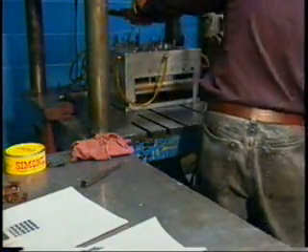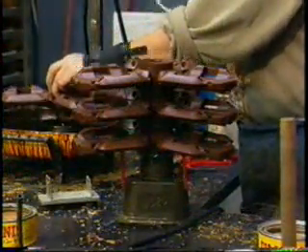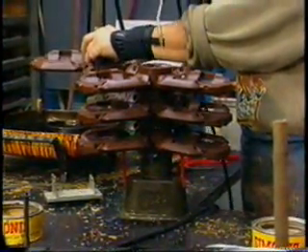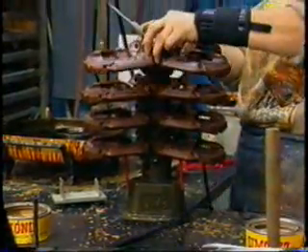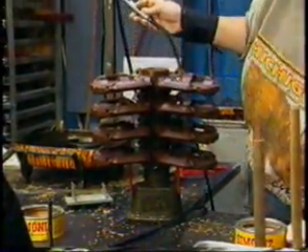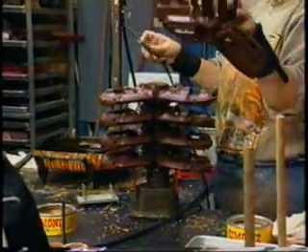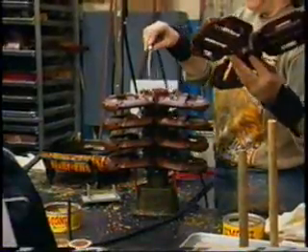Investment casting patterns are made by injection molding. These patterns are assembled onto a wax post connected to a pouring cup. This pattern assembly, called a tree, usually incorporates complex runner systems to assist metal flow in the investment casting process.